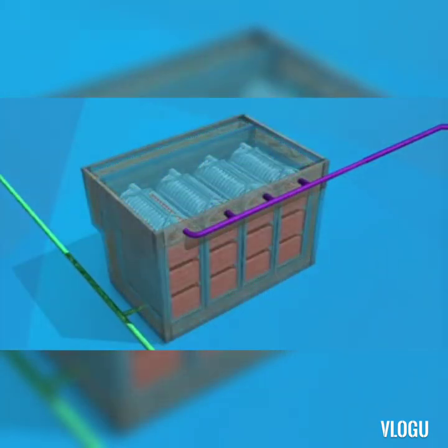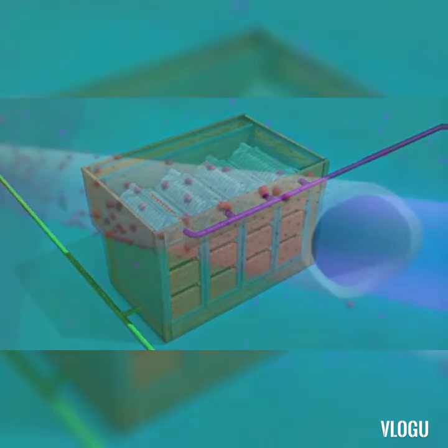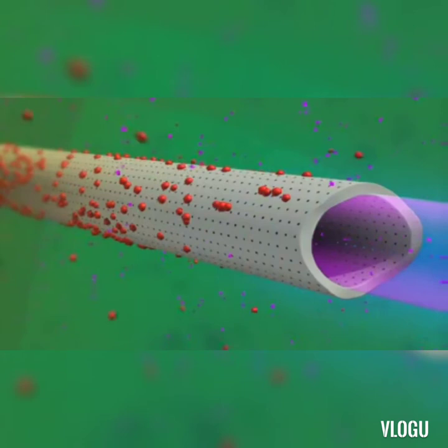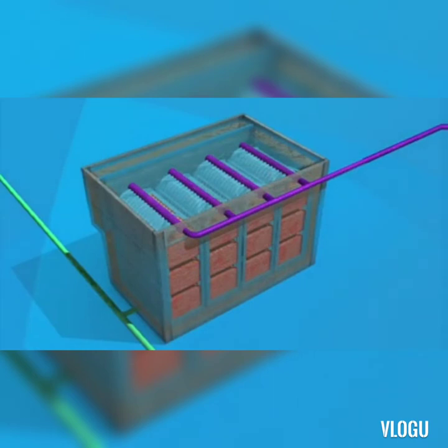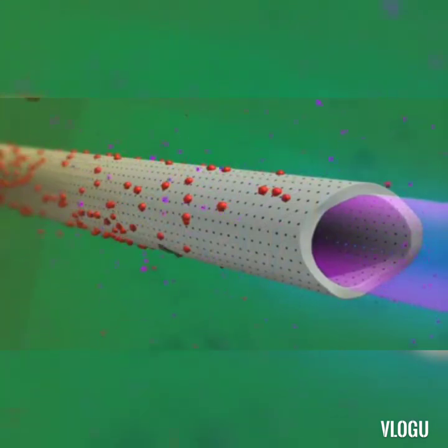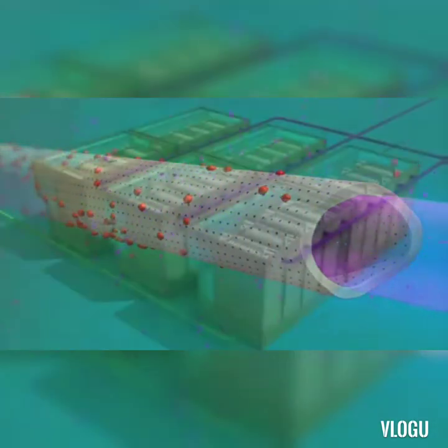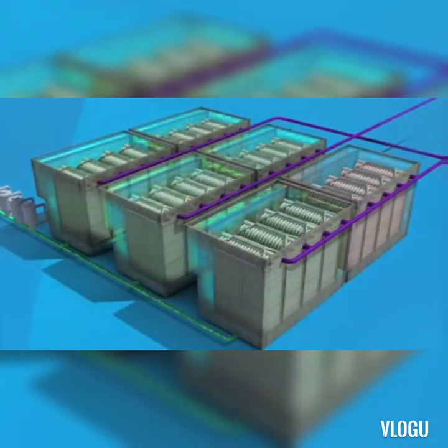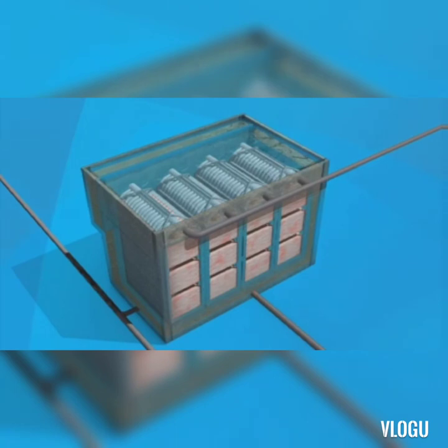After a period of operation, the fibers become blocked by the retained particles. This restricts the flow of water. The fibers are cleaned through cycles of backwashing and chemical cleaning. Backwashing pushes some of the filtrate through the manifold header into the cassettes and through the membrane pores to dislodge any stuck material. The backwash cycle removes particles blocking the membrane fibers. The backwash cycle occurs every 20 to 30 minutes in one cell at a time to allow the other cells to continue working. In addition to backwashing, chemical cleaning cycles remove any material still stuck to the membranes.